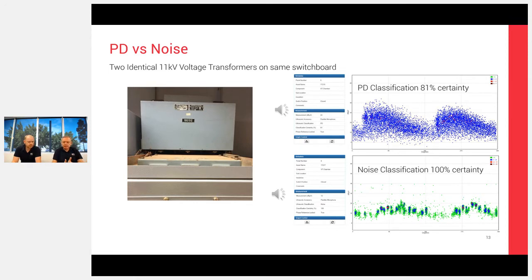So with that one, it's more of a mechanical, magnetic type noise. The sort of thing where you're almost saying, yeah, it sounds like transformer noise. It's again phase lock though. If you look at the patterns that we've got on that phase lock, you'll see there are some very tight clusters on there. So you've got some very dark spots, but they are really tight. So when we see this very tight clustering, that's almost something that's happening in a machine type way.